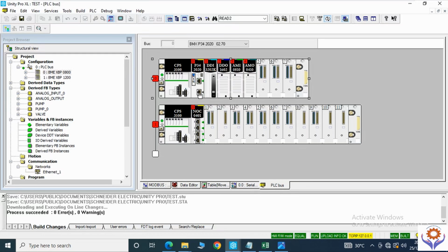If the flash has some gaps between each one, it means it is trying to transmit from your side, but it is not receiving any feedback from the slave devices. So based on your LED blink, you can find out. I will attach that video at the end of the session, showing how it blinks on the devices.